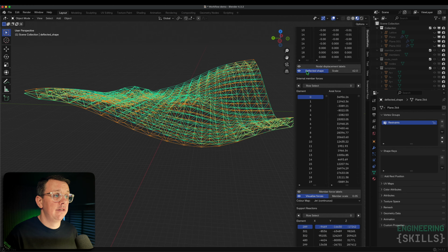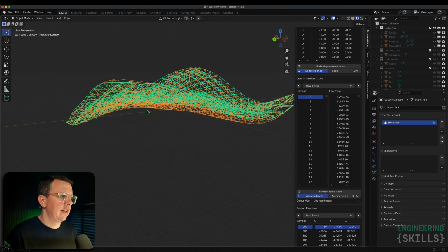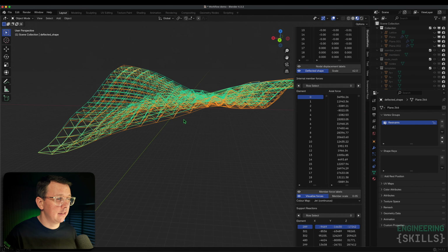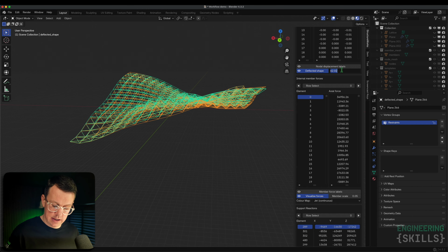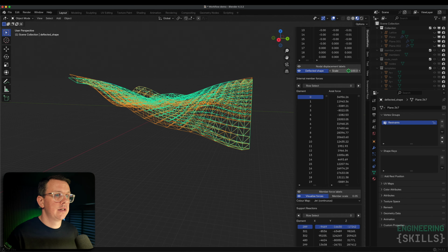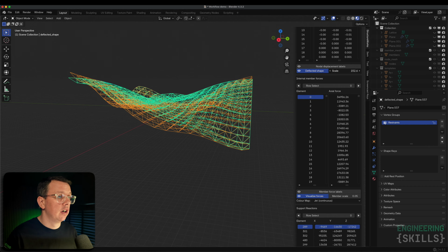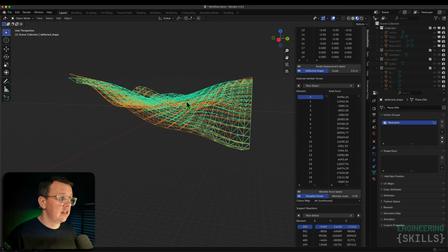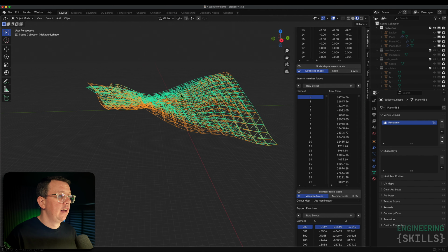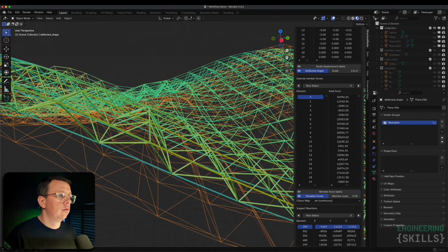So let's take a look at the deflected shape. So we can see we've got a deflected shape here. Again, it's kind of difficult to see the influence or to see that deflected shape here like this. What you can do is scale it up. Let's put the scale at 100, and what I think is really helpful is to now start sliding this back and forth, and that gives you a sense, an intuitive sense, a qualitative picture of what that deflection wants to do. Of course, you could dig into individual nodes and look at the displacement of those nodes. I think another thing I'm going to add fairly soon is a displacement heat map similar to the force, the axial force heat map. Again, that'll just give you a bit more of a visual, a quicker visual picture of what the displacement looks like.